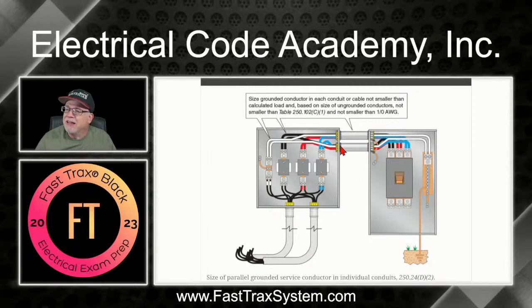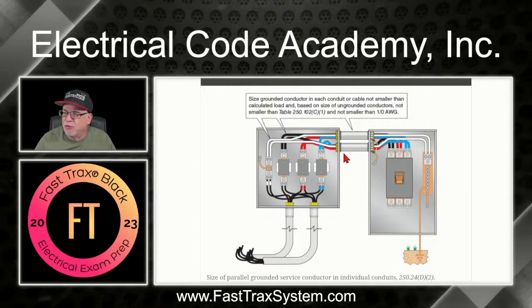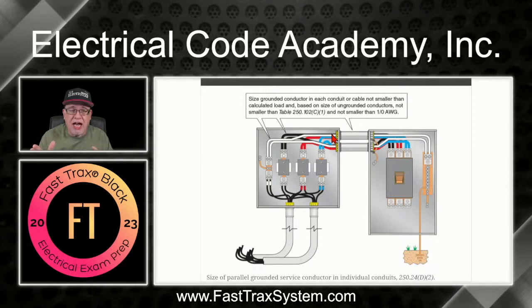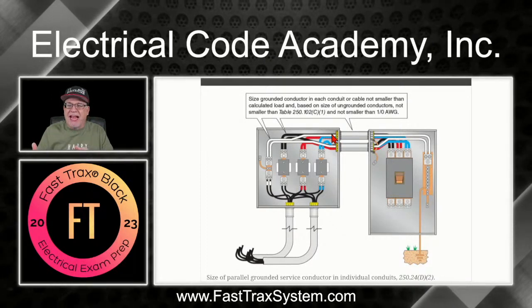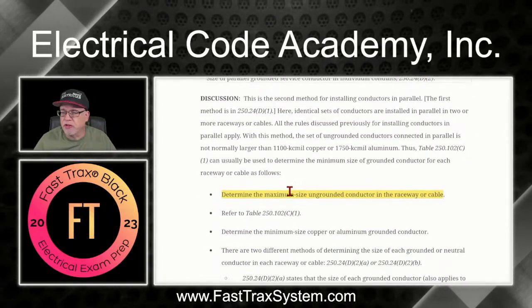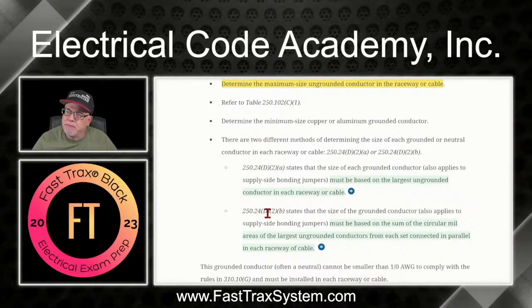All right, so that's what we know. So we've done that so far. So we know at least it's got to be at least a 1/0. And we're going to compare that to our load calculation, okay, and see which one results in the larger conductor. Now,